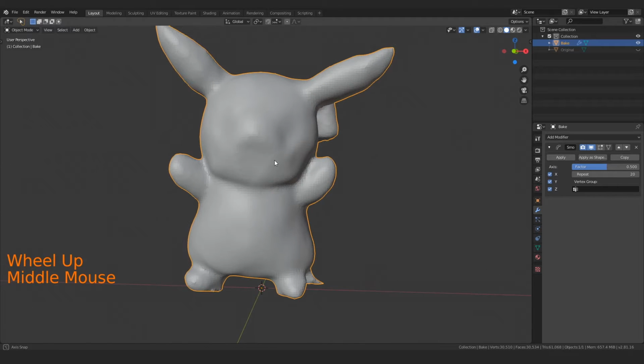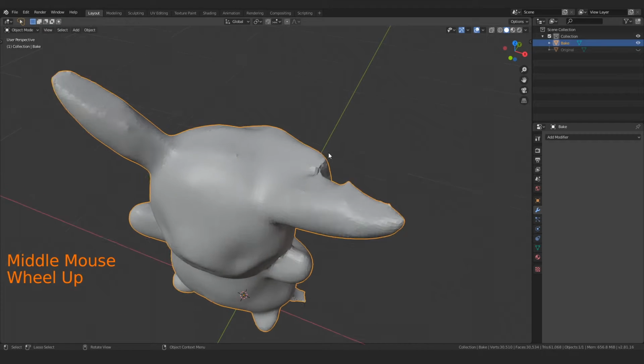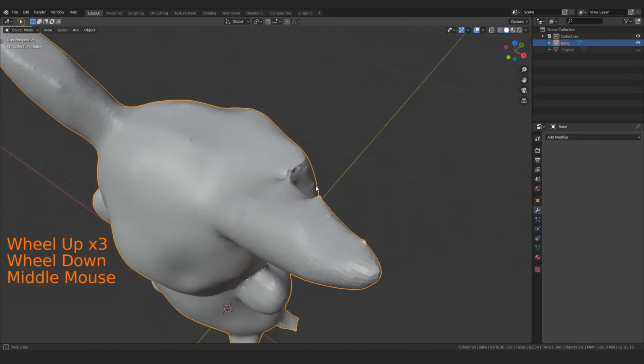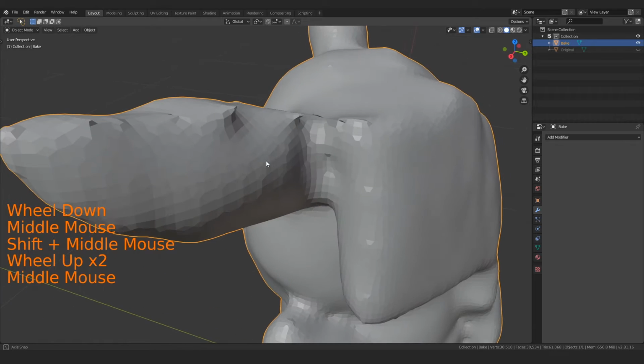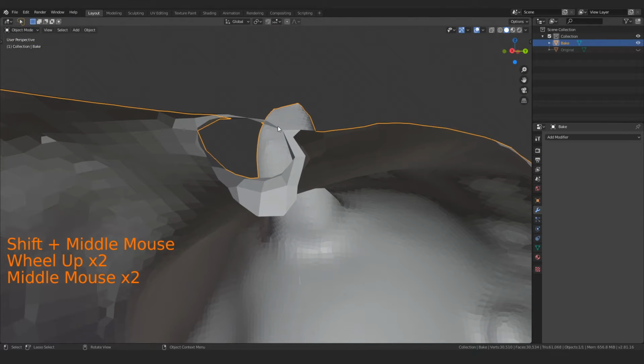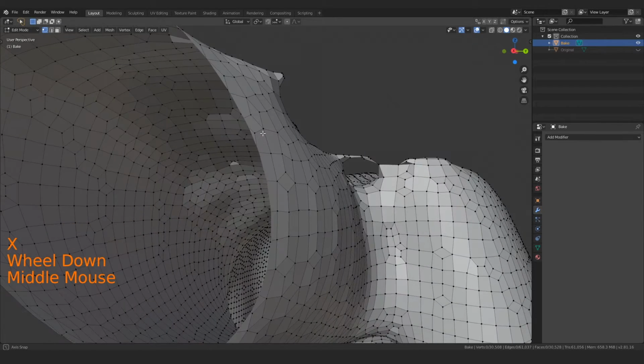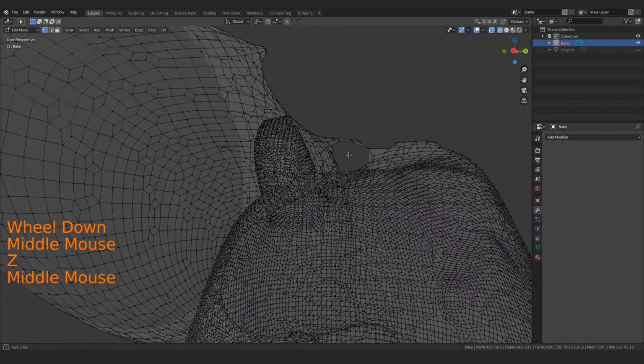So for me, having this smooth model is good enough. So I'm just going to press apply here. And so now I have this very smooth Pikachu. Again, I could go back into the sculpting mode and smooth out some of these points here. It's actually created this weird geometry here, so I might have to come in through here and delete some of these points just to clear up this weird bridge that it's creating.